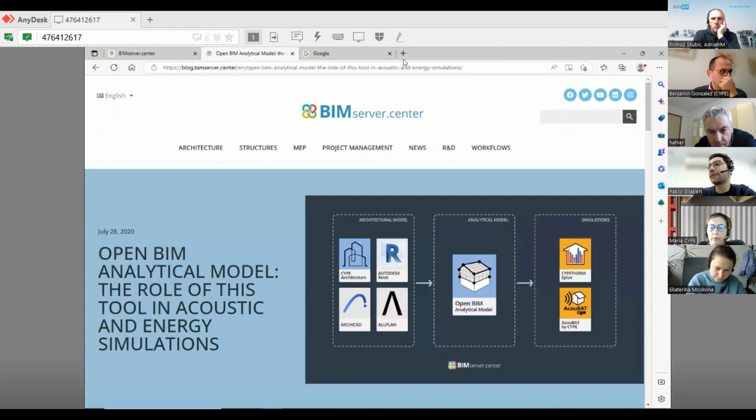We have done a really interesting exercise in order to create all the 3D entities connected to the right entities of IFC and make it possible to import them according to the entities that Revit identifies, because Revit is not able to identify all the entities defined in the IFC. So we are mapping in order to import this information into Revit in a proper way.